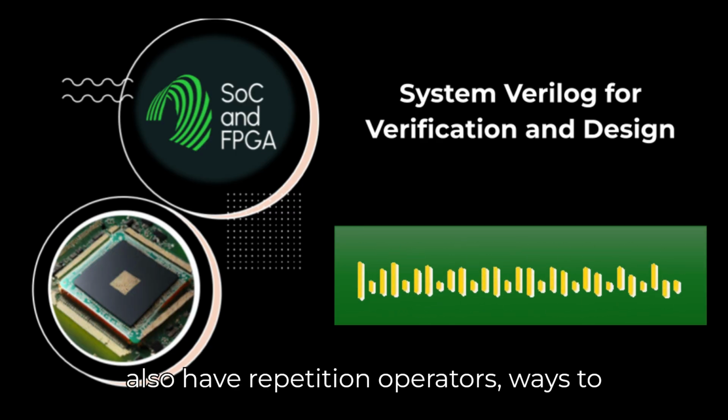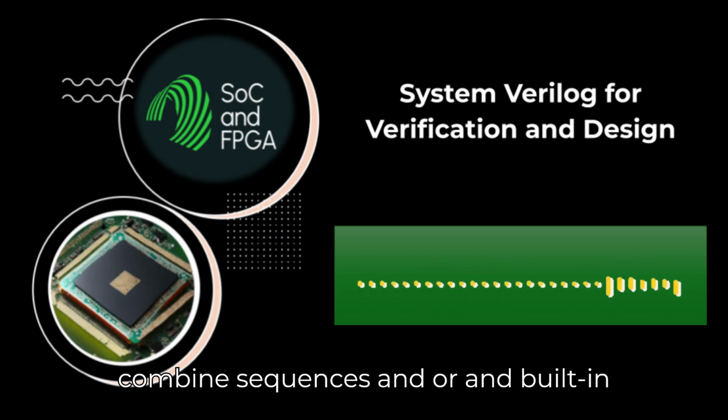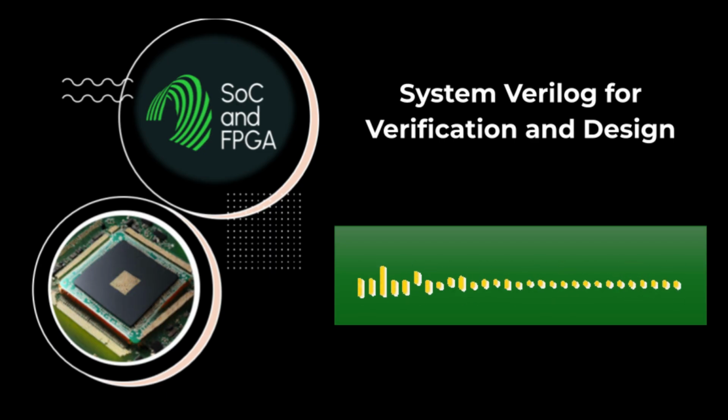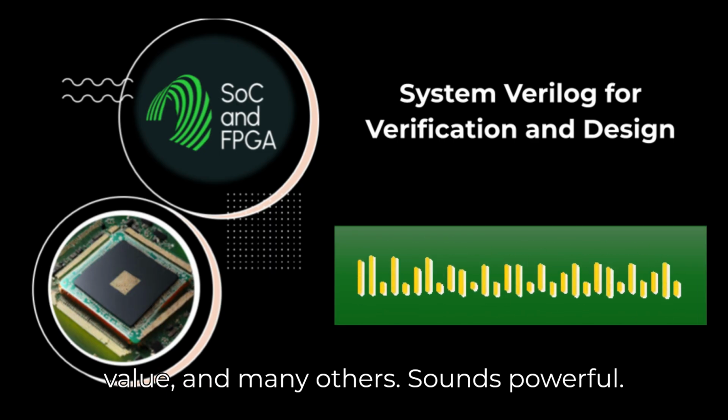Very. You also have repetition operators, ways to combine sequences, and built-in system functions like $rose(sig) to detect a rising edge, $fell(sig) for falling edge, $stable(sig) to check if a signal hasn't changed, $past(sig) to get a previous value, and many others.